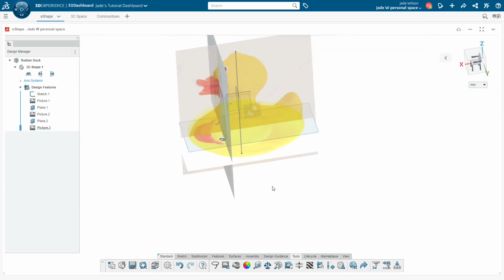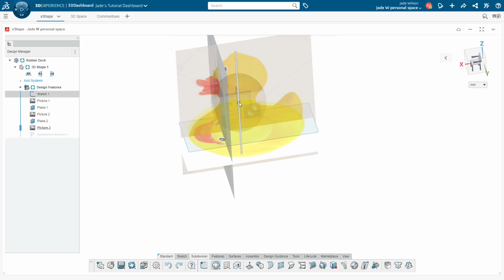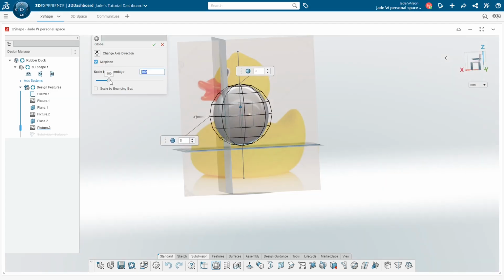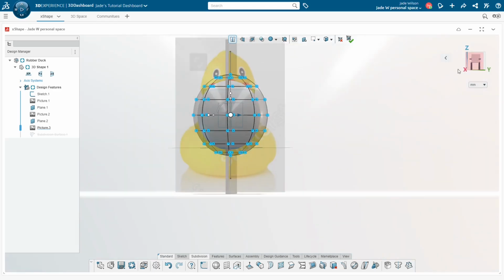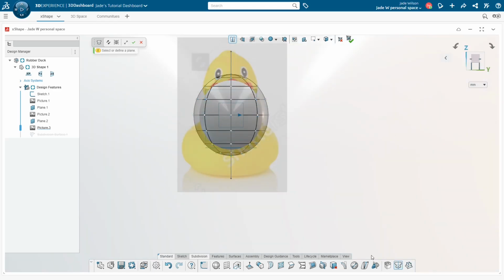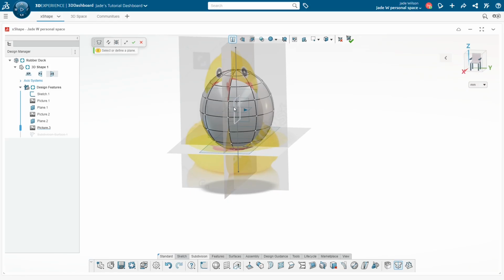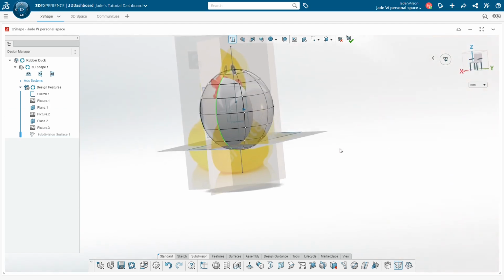For the main duck body, I used the globe surface as the starting shape and snapped it onto my guide sketch. I switched on the symmetry tool along the ZX plane, that way I can edit the shape on one side and the duck will remain symmetric. A green line here shows me that the symmetry feature is active and along which line it is mirroring.